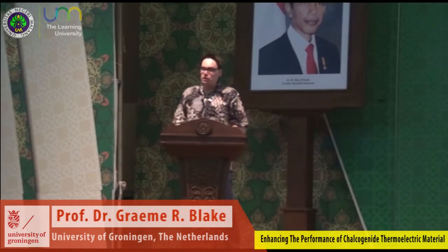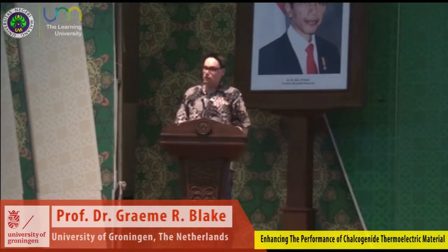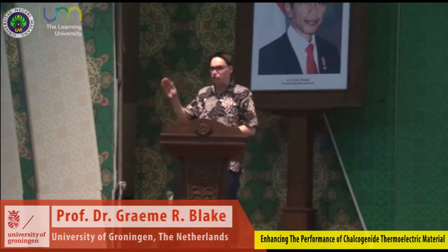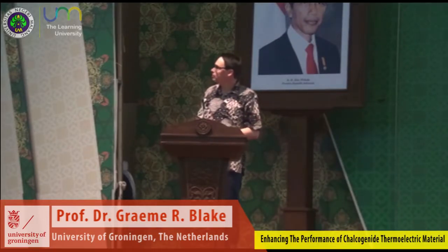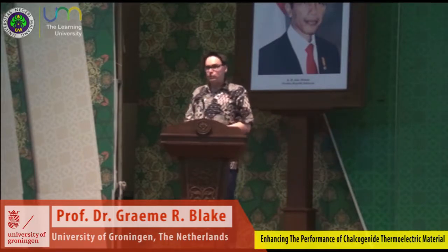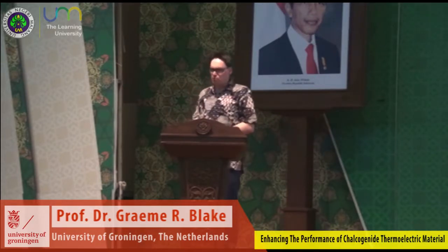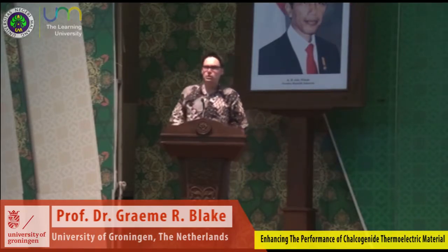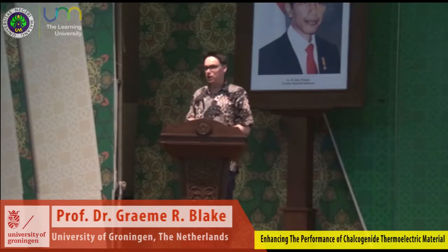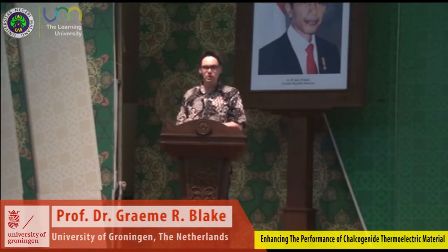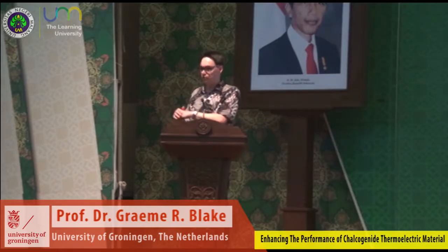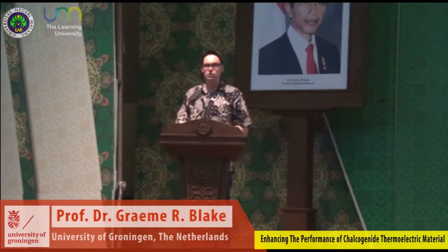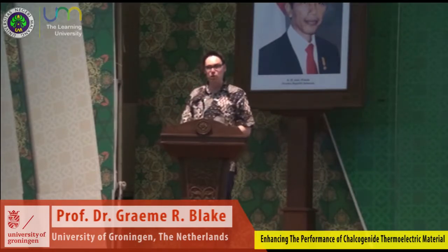One other thing you can do in the TAGS materials is to modify the electronic structure by chemical doping. So this has been reported in the literature for just 3 elements, cerium, ytterbium and dysprosium. And you can increase the performance by about 25%, and it's poorly understood why this happens. So these are dopants with magnetic moments, and it's thought that the magnetism of these dopants may have something to do with it. If you have magnetic moments in the lattice, you may favorably scatter the charge carriers in some way. But there's been very little theoretical study done on this, so it's unclear why it works.